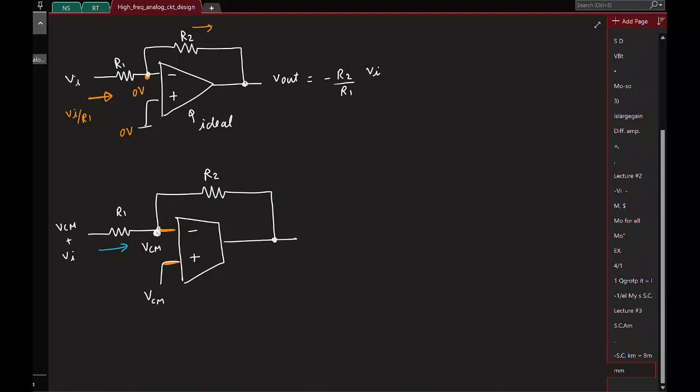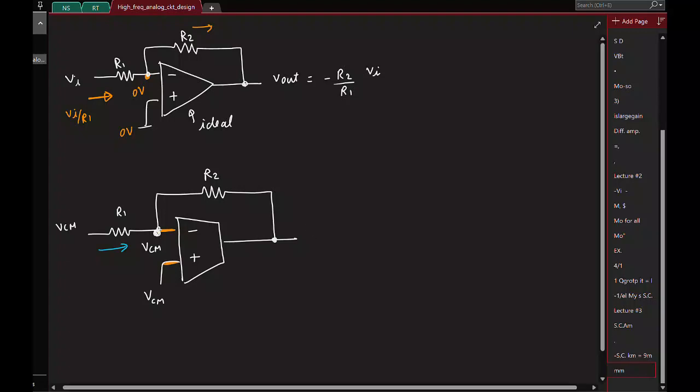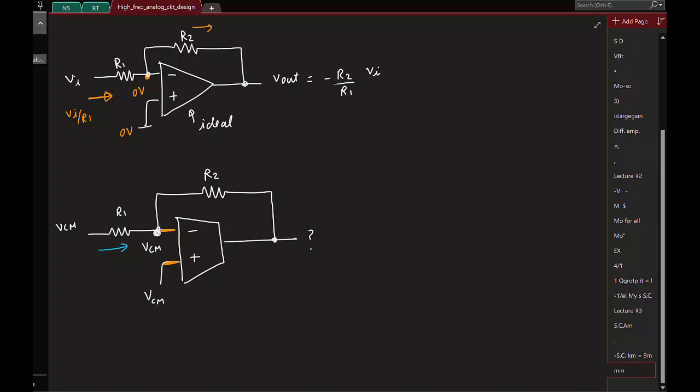So yeah, so let's say now I don't have the input, I just apply the DC bias at VCM. What will be the DC voltage at the output? Is it ideal? It's a GM block. Yeah, assume it's ideal for now, as infinite gain. Why? The current is 0. So the point is simple, right? The current flowing here is 0. So which means 0 current flows here. One end is VCM, other is also obviously at VCM. Fine. Now on top of it, you'll apply a small signal Vi, and that's what will generate the required stuff. Okay.